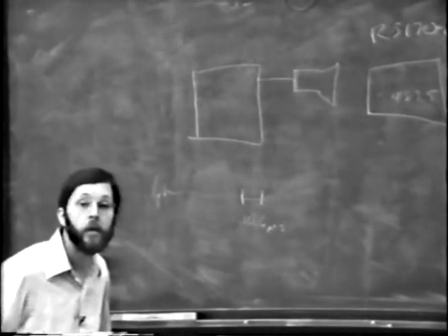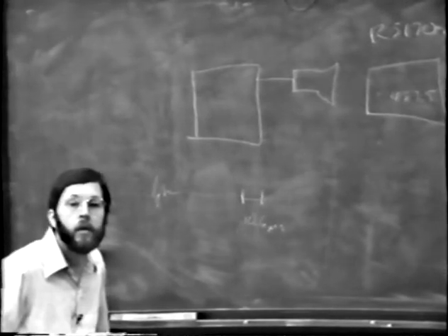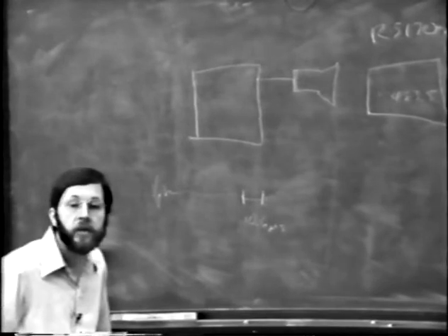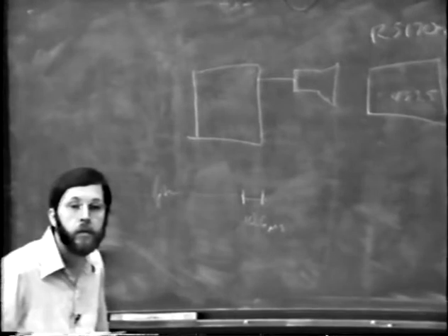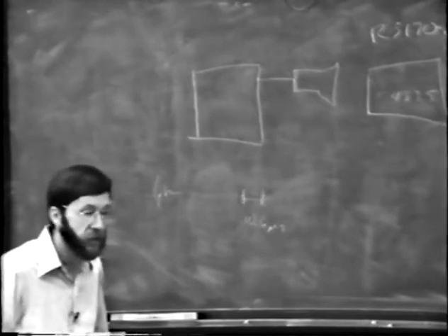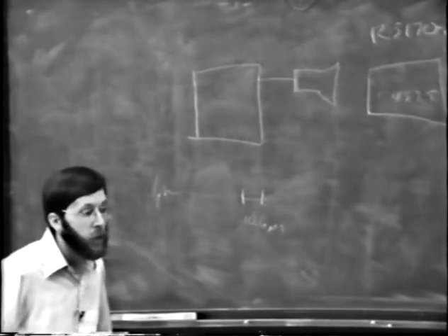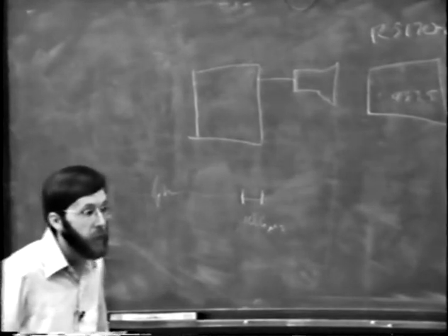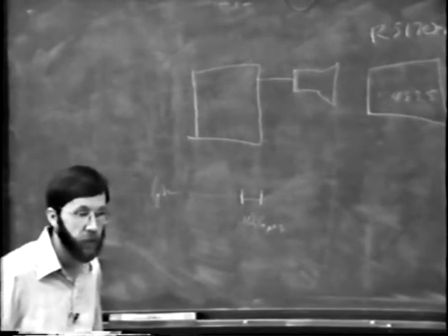Go ahead. Just a technical thing is the PDP-11's memory mapper won't let you map fewer than 64 bytes at once. That's correct. So you can't put these devices closer than 64 bytes to each other if you have more than one on the bus. That's right, that is correct. We had them separated by 64 bytes. And on the VAX, there was no problem. Again, we just mapped it into the user's address space.